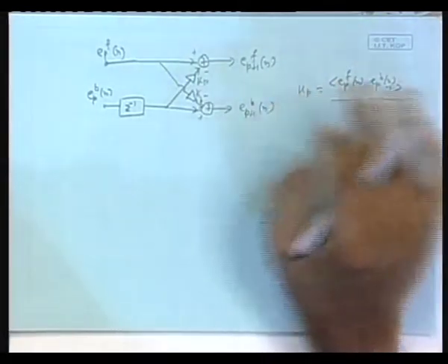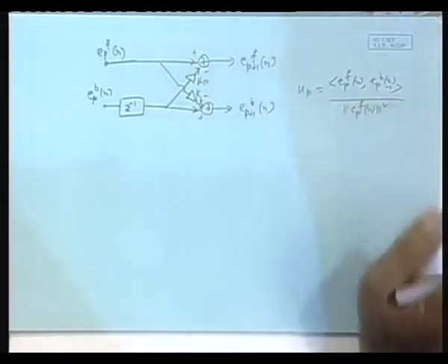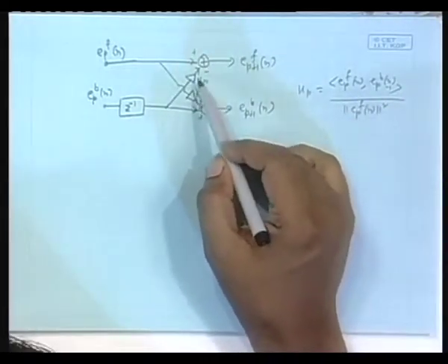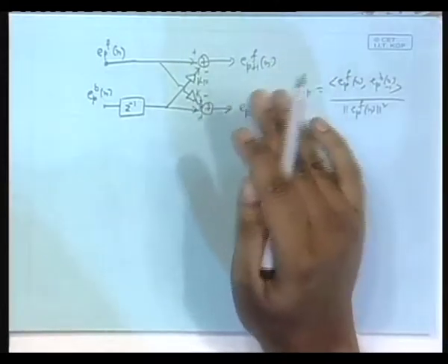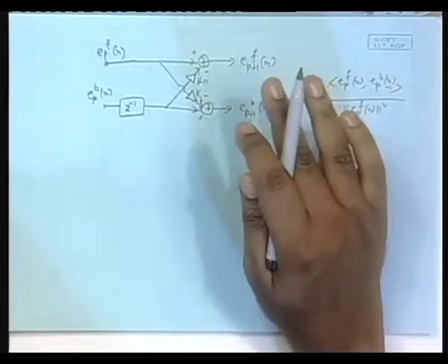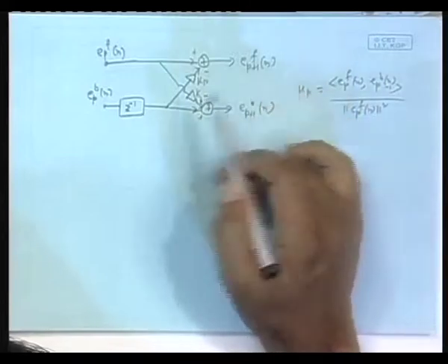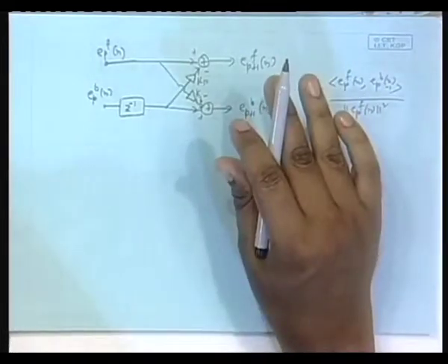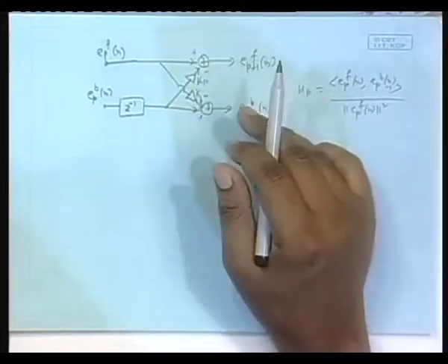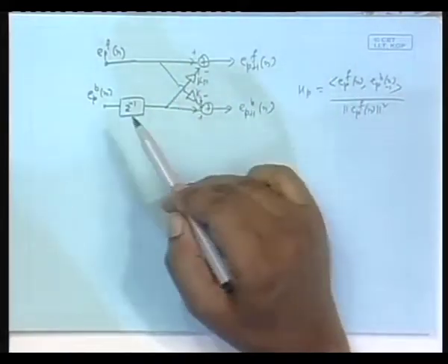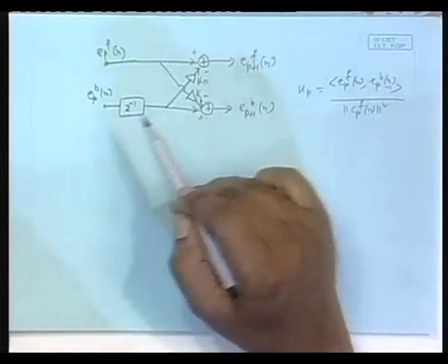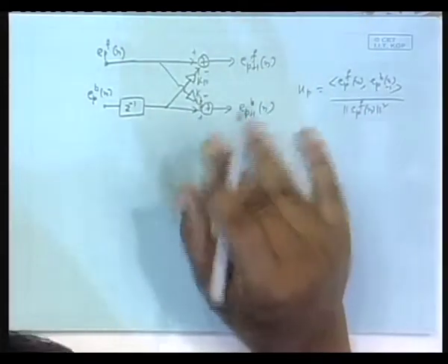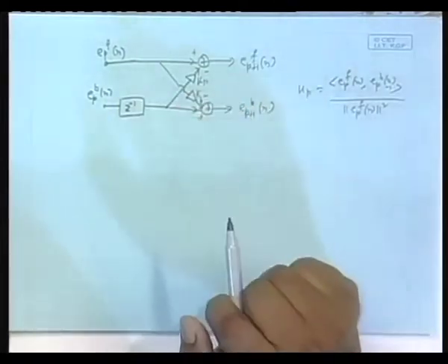But when the correlation is not known or is changing with time, then you have to have an adaptive mechanism by which the multipliers adjust their values in an iterative manner, iterative in time, so that they finally converge on their optimal values, at least in mean, as we did in the LMS case. And if there is a subsequent change in the input statistics, it will again track because it is adaptive. So, we want to march towards that adaptive version of this lattice now.